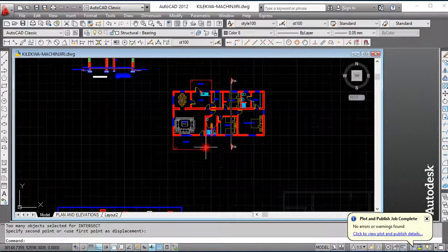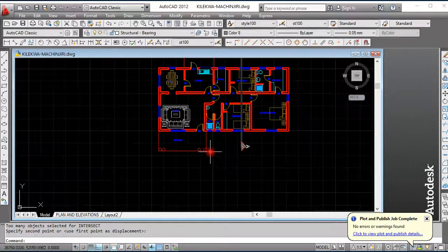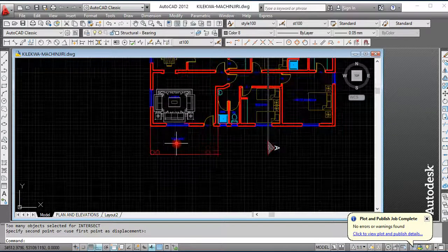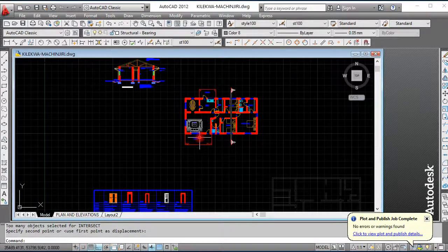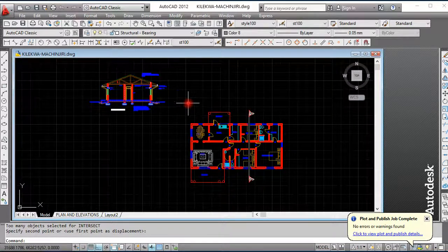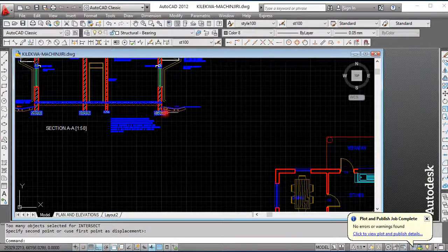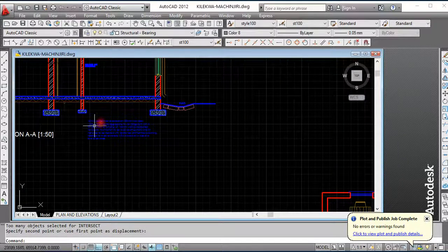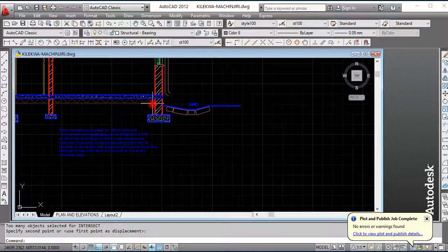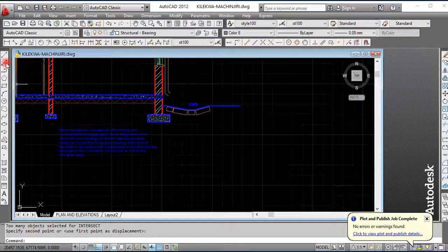Of course, we also need the roof plan. The roof plan is important in this case. However, what we'll do is just look at the part below and maybe some little heights. But the roof plan is important as far as we are concerned. So the best way to do this is to come up with the construction line. Since we are not going to see the foundation, that is the superstructure only, we can come up with the construction lines which will go through the crucial points. So this is our construction line.